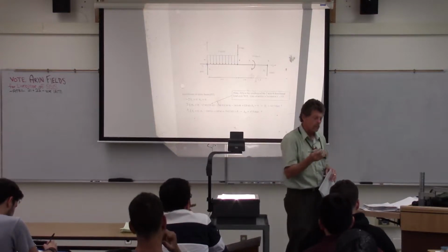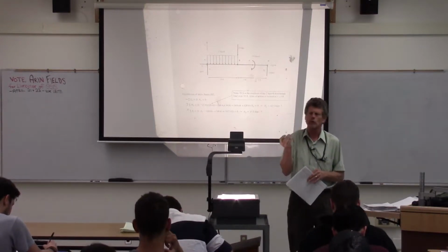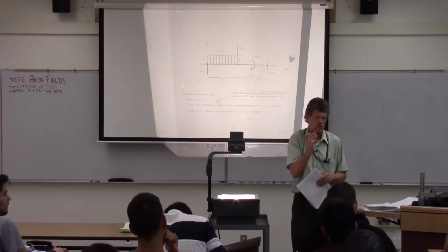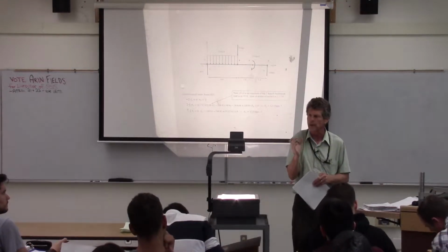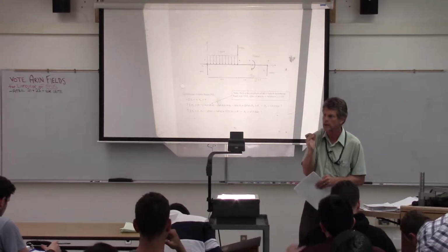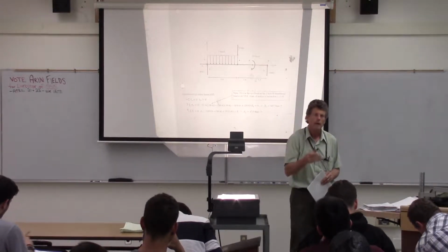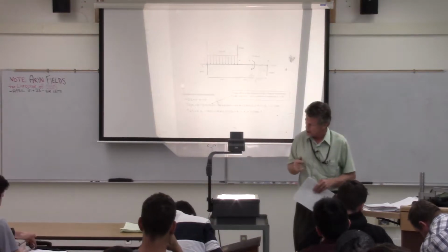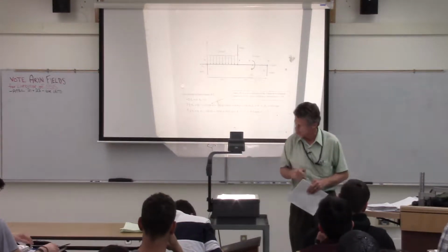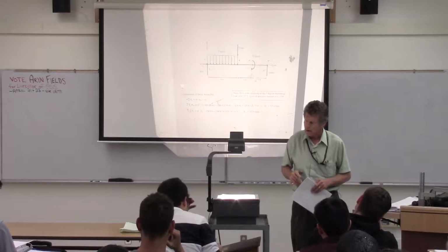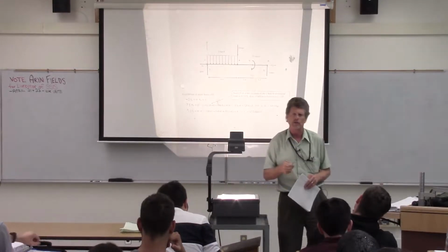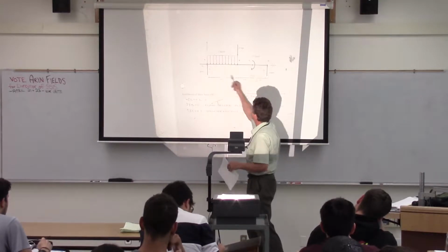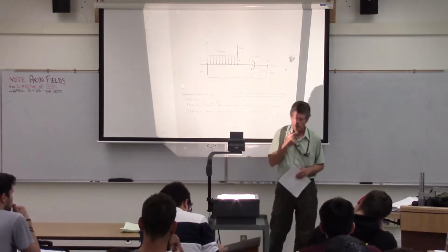What we're doing now, remember, we've gone through the calculations, and you did in your homework basically calculating those forces somewhere on the interior of that beam. So we've looked at that concentrated couple or moment, shear force, which now is going to be perpendicular to the axis of that particular member, and then axial force if there happens to be any. Now, most beams are going to be flat, so we're not going to really be looking at axial forces. But this is basically going to be our starting point.